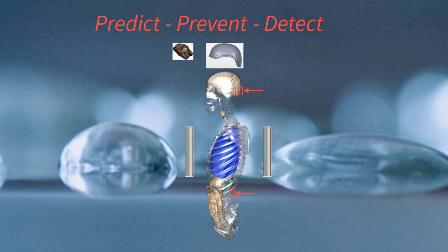And here small squares would go around that scarring as shown by the red arrows, and also recalibrating the in-service pressure sensors to detect that critical pressure of 30 megapascals.